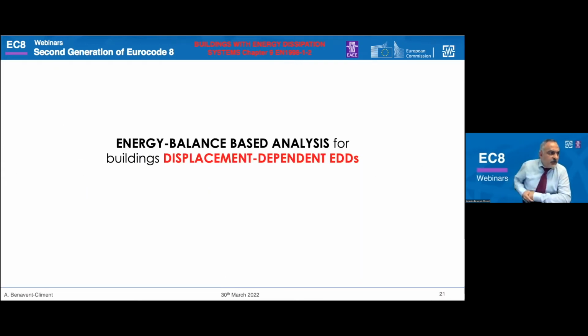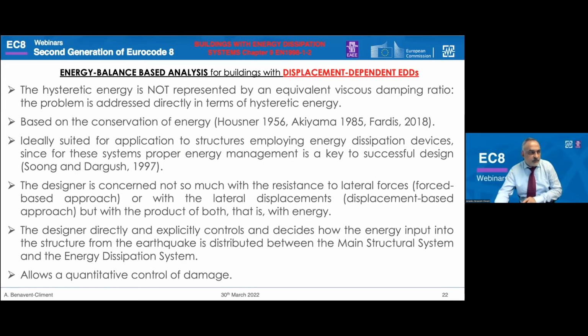Now, finally, let's focus on how the energy balance-based analysis makes the verification of buildings with displacement-dependent dampers. In this method, the hysteretic energy is not represented by an equivalent viscous damping ratio. The problem is addressed directly in terms of plastic strain energy. This method is based on the conservation of energy and the works of Housner, Akiyama, and others, and it is ideally suited for application to structures employing energy dissipation devices, because for these systems, a proper energy management is a key to a successful design.